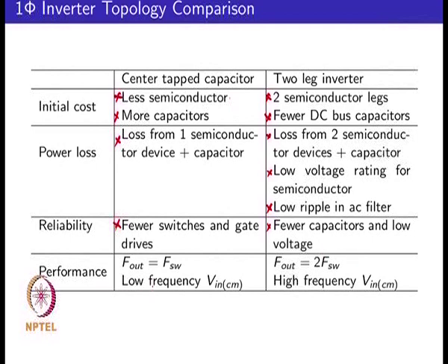We also saw that in the center tap topology you have essentially DC in your input common mode voltage, whereas in modulation method 1 there is high frequency in the common mode input. So, you might need more EMI filtering. So, you could actually now, on an overall system basis, look at what it takes to do a comparison.